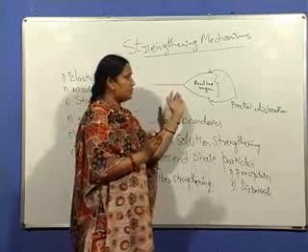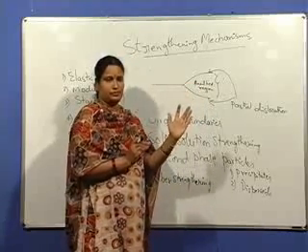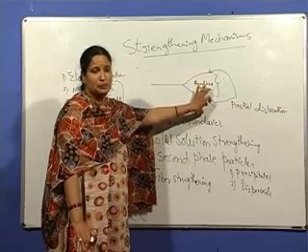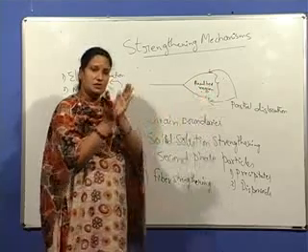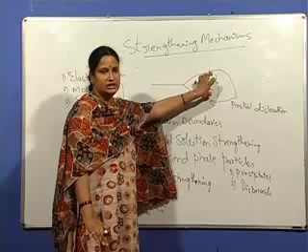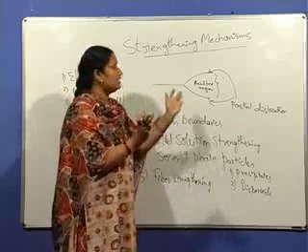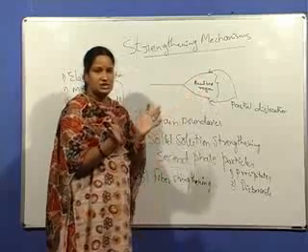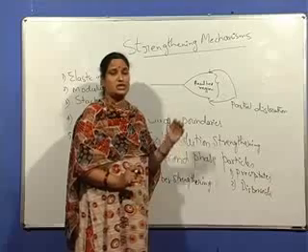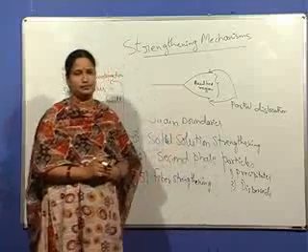For this partial or extended dislocation to move as a unit is very, very difficult. If it has to move as a unit, the stacking fault energy should be very, very high. Because if the stacking fault energy is very high, these two partial dislocations come closer and the width of the faulted region will be less. If the stacking fault energy is low, the separation between the partials is larger. So it is very difficult for this extended dislocation to move as a unit because there are many constrictions.